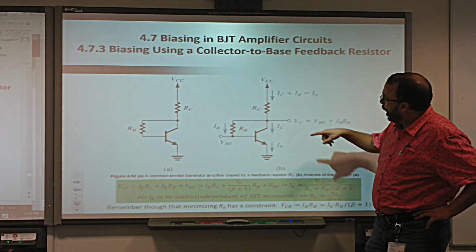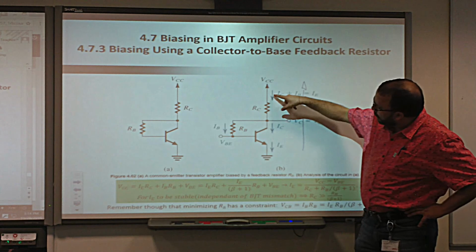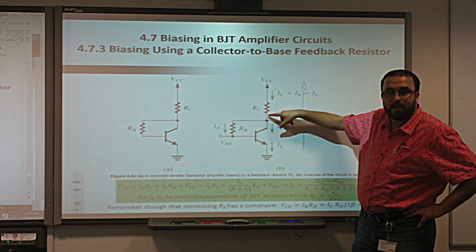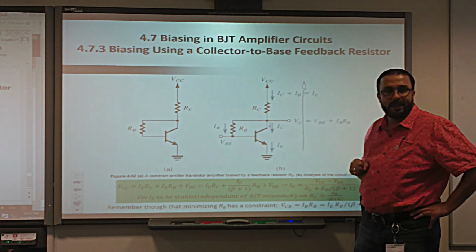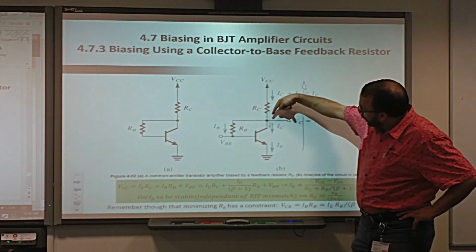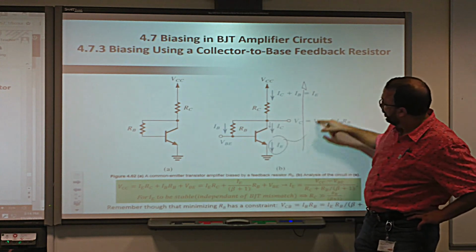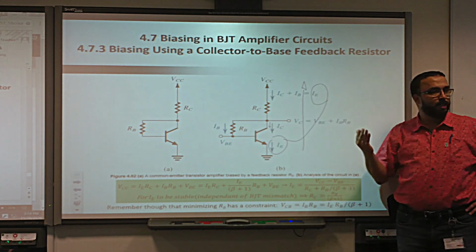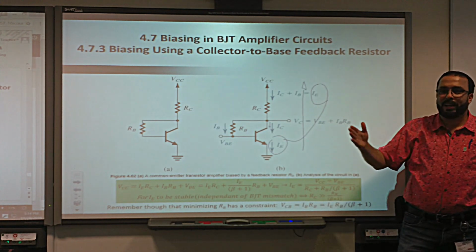So now, the total voltage in here, before I go there, look at this current. The current that is here is not IC. This is IC. It's actually the one that goes inside the collector. This one is actually IC plus IB, which is nothing but IE. Yes or no? What comes in must go out. What goes around comes around.